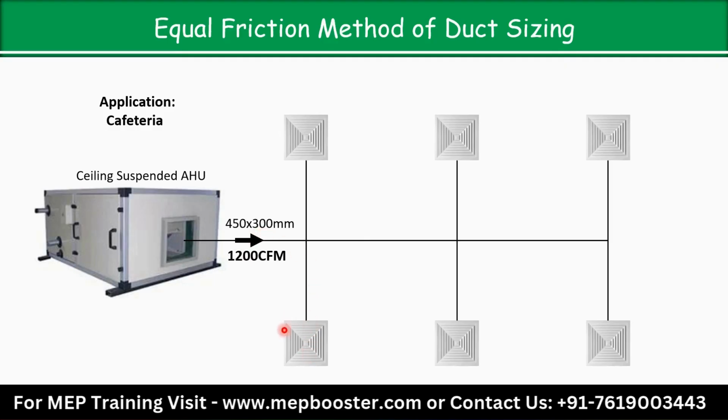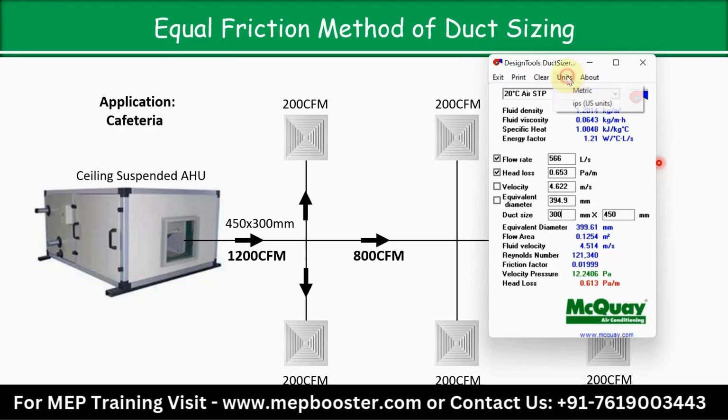Now we are supplying 200 CFM in this diffuser, 200 here. So the remaining CFM is how much? When you see, 800 CFM. So for 800 CFM, how much duct size? Again open it and change the unit first to IPS and write down here 800 CFM. Head loss we have to keep constant. I have taken 0.08 only, and now I'm changing the unit to metric.